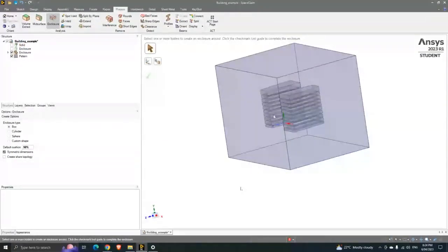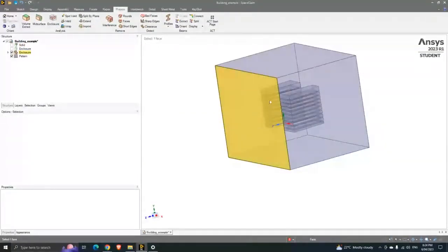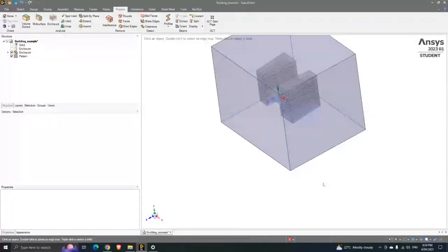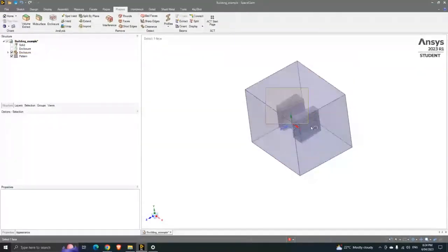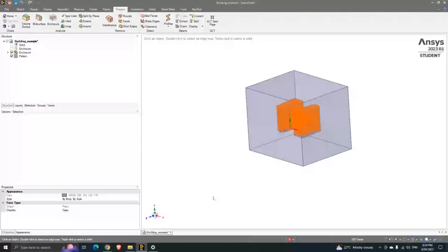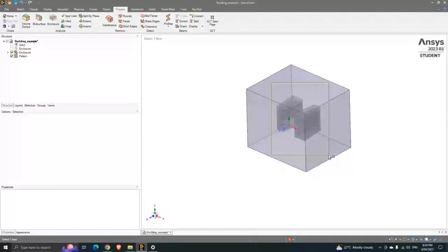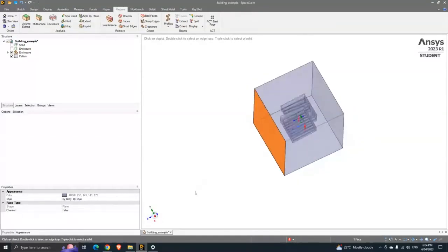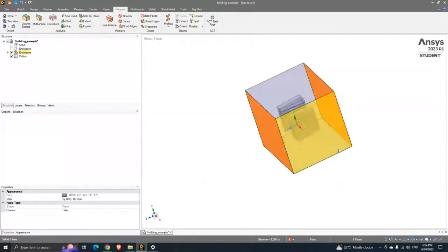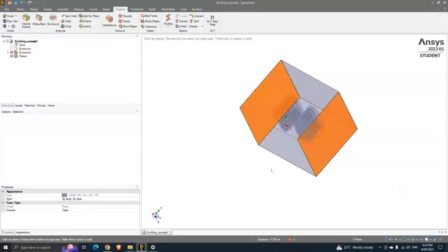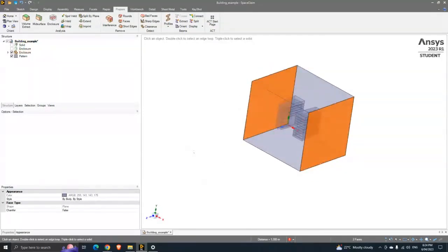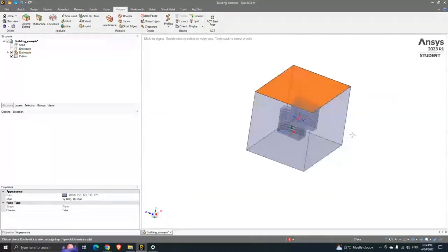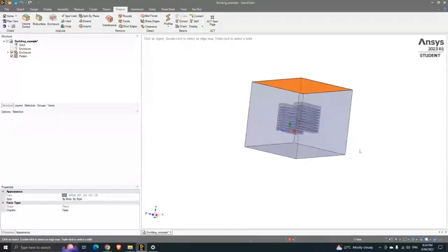And what it has done is it's created a geometry. This is the fluid domain where we have the body of the building geometry. Then we can have the flow inlet over here, the flow outlet over here. These two we can assume are symmetry. Here we are looking at flow flowing normally to this building. This can be the sky.